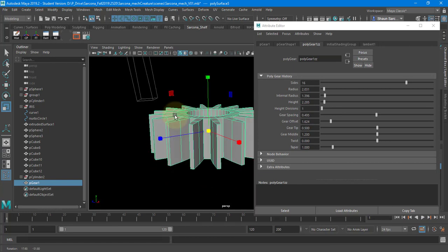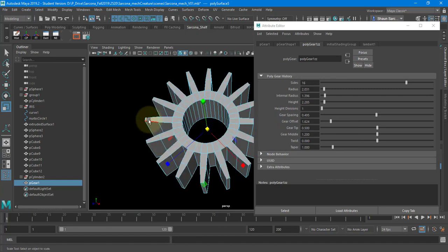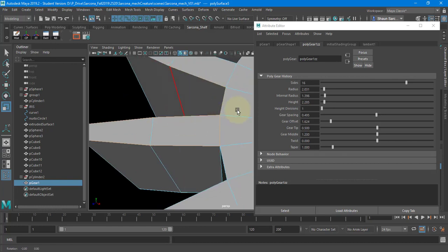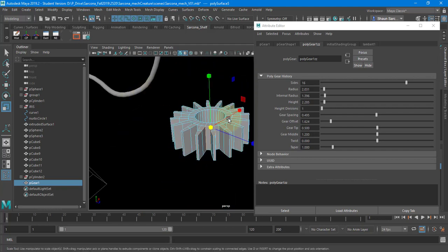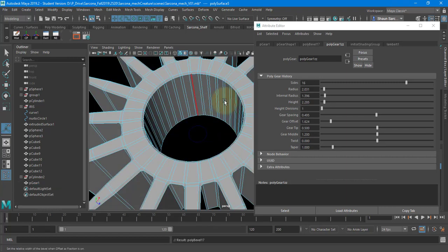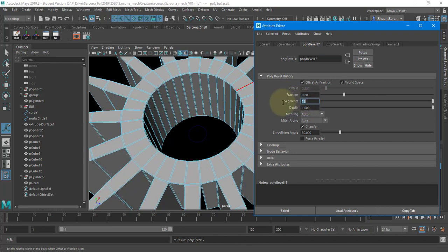If you're going to use, let's say, this hinge in 15 different spots, do all your beveling ahead of time. Okay, you don't want to duplicate this 20 times and then realize you need bevels, because that would suck. So I would go through and bevel like everything on here. I'm not going to select all of the stuff, but all the way around this area here, down in these crevices, and so on. You can't just grab the whole thing, because then you'll grab these middle pieces and then it won't look good. Bevel edge, 0.2, oops, 2 segments, not 12.